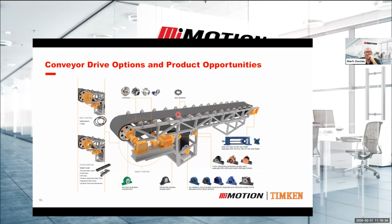So your V trough shape allows the product to get from one end to the other and stay in the center of the belt. On the bottom of the belt, you'll see there's what we call return idlers. They're spaced out at a much larger spacing. The trough idlers obviously have to carry the weight of the product that is on the belt. On the bottom side, the return side, it's not as heavy because it's just literally the weight of the belt itself.